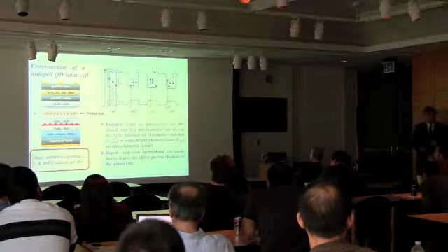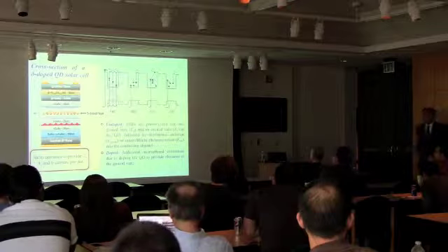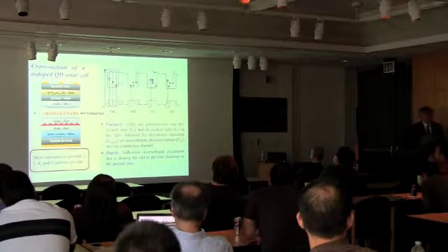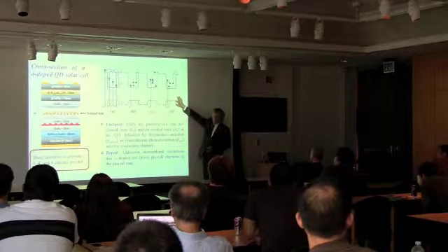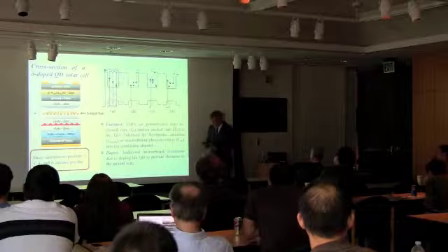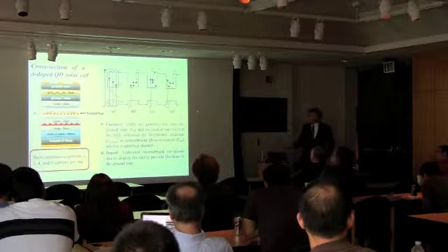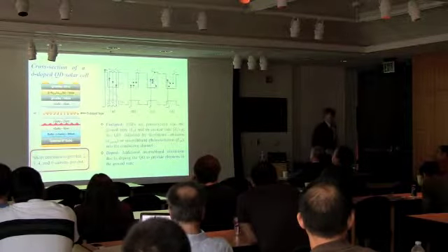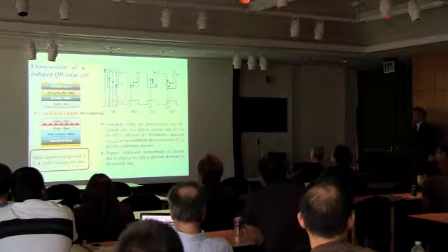In case of gallium arsenide, what is going on? The capture of electrons into the dots is 10 times faster than capture of holes. And also, as you see, and it's to some extent to scale, the depth is small for holes. There the depth is large. So when an electron is going in, it's practically in. When a hole is going in, it's easy to go out because there is a very small barrier for them.